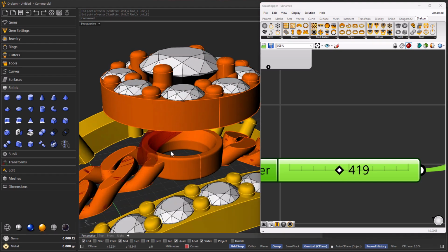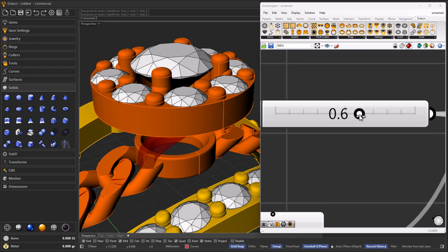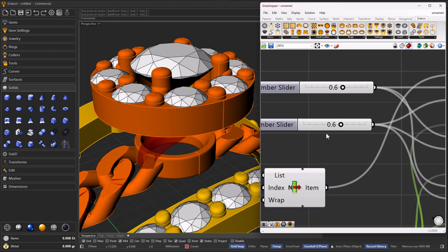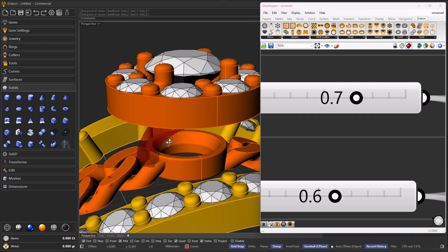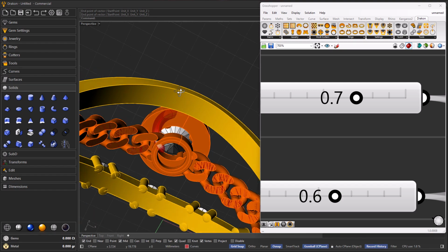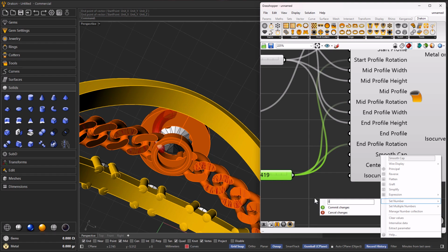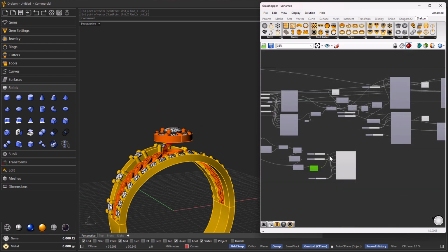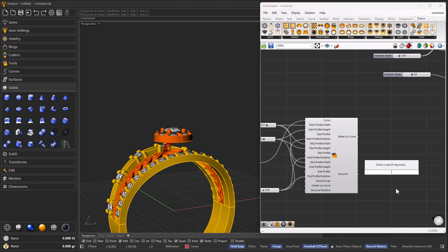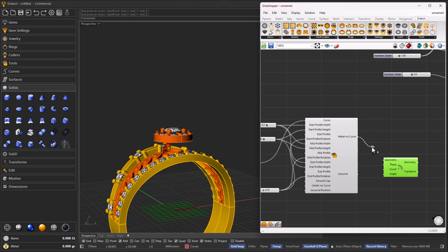So I rotate just to make sure it's fitting on the object. And now if I adjust either the thickness or the width, as you can see, it will adapt. So what I'm going to do is reduce here a little bit the smooth cap. Instead of 1 millimeter, I'm going to use maybe 0.2, should be enough, and we can increase or decrease. But now this is one curve that I'm going to, what I'm going to do now is to create a polar array of this.